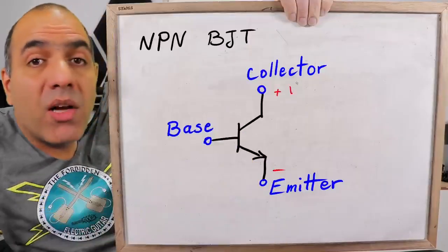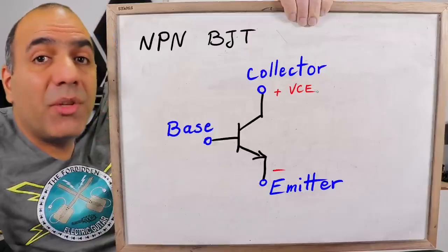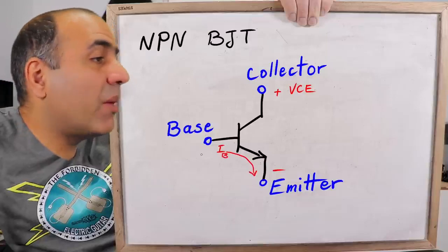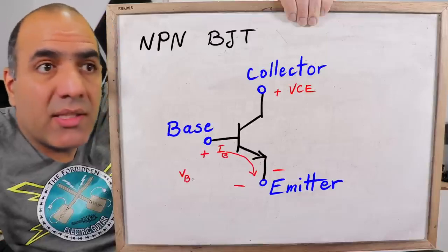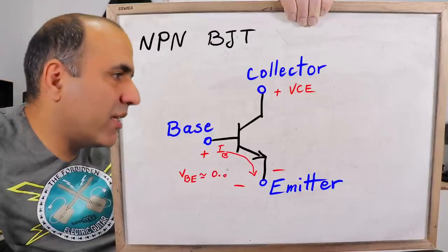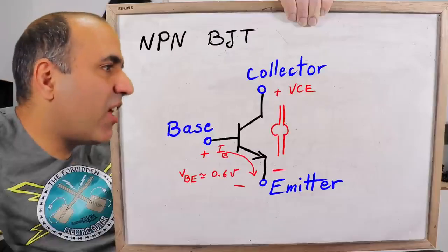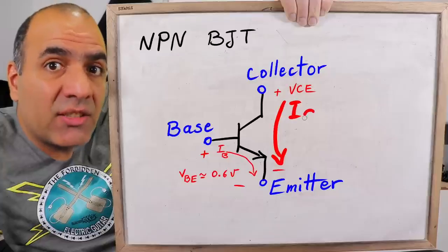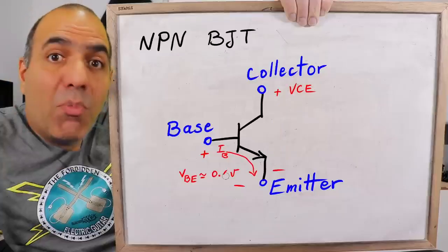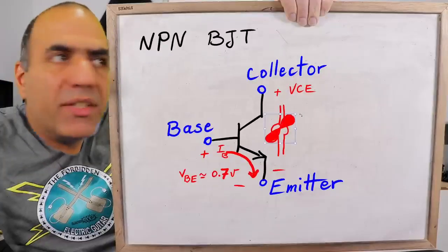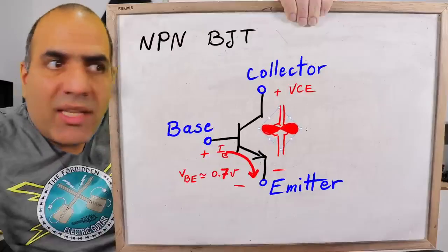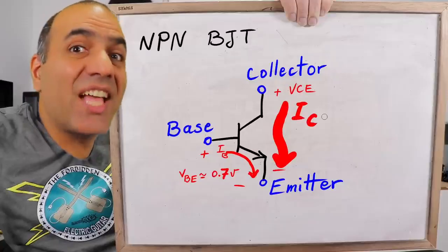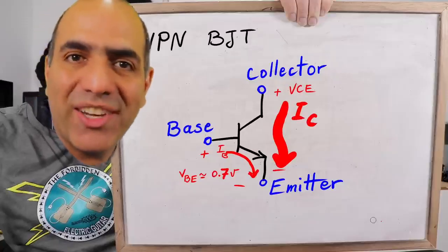If you place a positive voltage across the collector-emitter terminals, then if you pass some little current through the base-emitter diode by placing, say, 0.6 volts across it, magically, it is like opening a valve between CE and a much larger current flows from C to E. The more current into the base, the more open the collector-emitter valve gets, and so more collector current. That's why I said BJT is like an adjustable resistor. End of story. No, there is more.